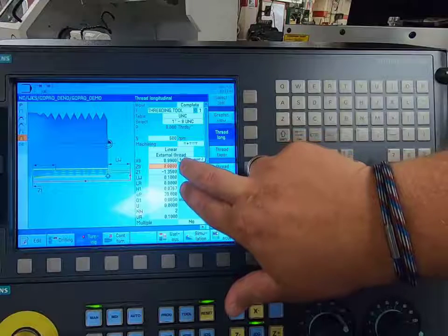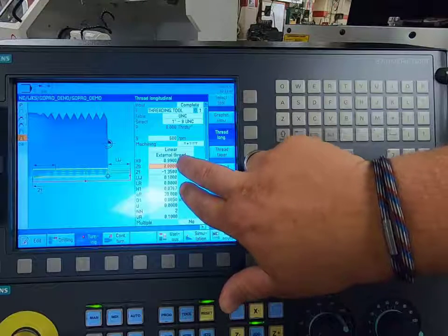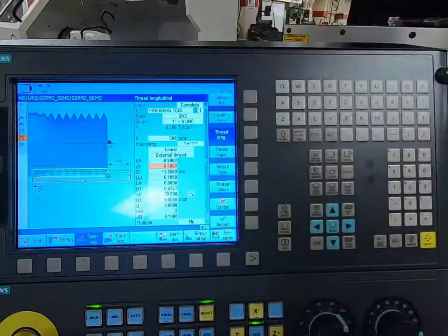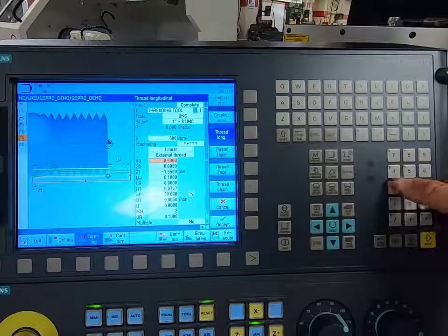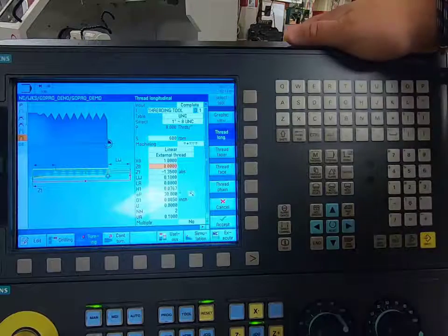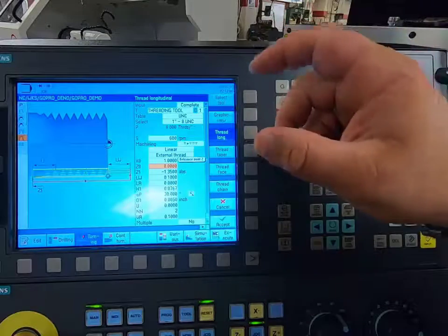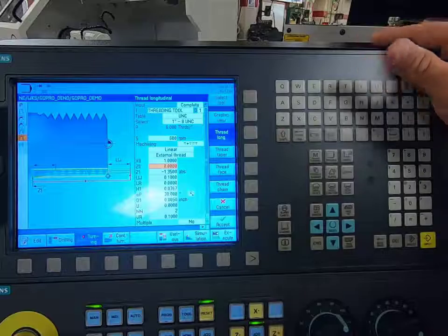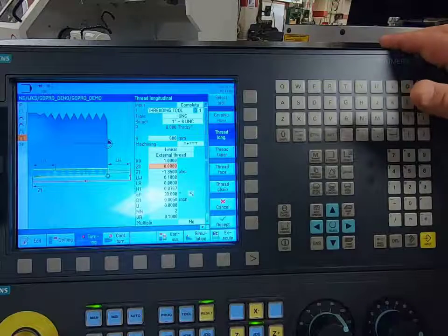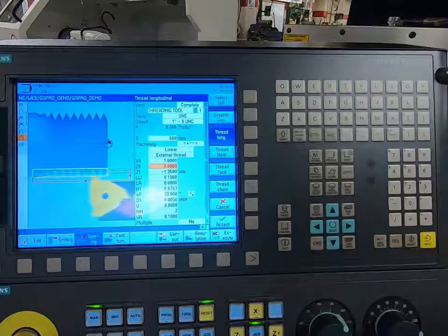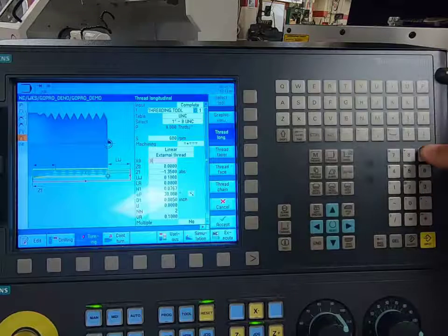It's only going to drop 76 thousandths from 990 thousandths. So if I told it was 1 inch, it would only drop 76 thousandths. Well, there's still that 5 thousandths left where I put the OD of that tool. Okay, and I can change things if I need to. So let's put this at 0.995.